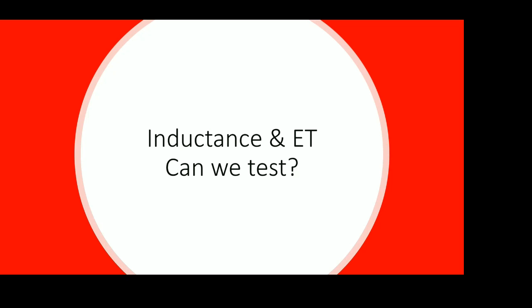In this case, they usually use it for waveform shaping, and that's what we're going to start talking about, why testing inductance on a PCB is more important now than just using a standard continuity test to make sure the traces of these inductors are working. But once you get those primary and secondaries to work together, you add a capacitive component to it, and you can actually do some waveform shaping.